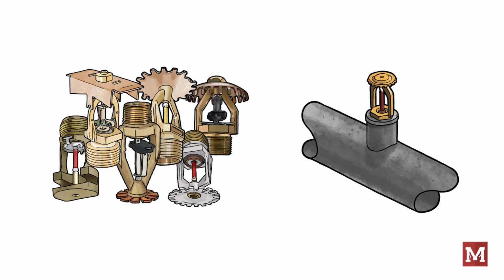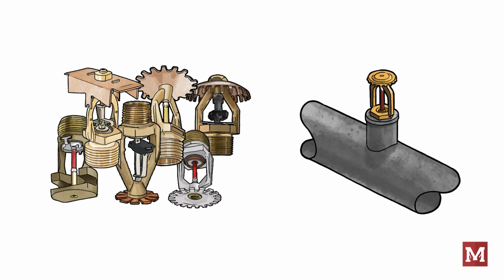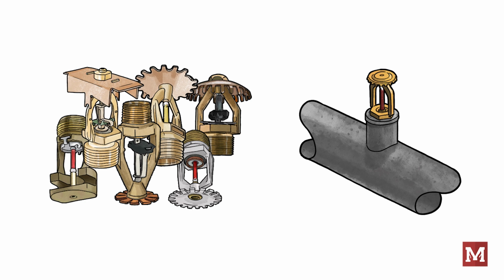Further, for non-standard spray sprinklers, extended coverage sprinklers, special application sprinklers, or sprinklers protecting high-piled storage in an ESFR system or control mode special application design, we need to know the pressure that the sprinkler needs to operate at. This can seem like a pretty insignificant data point, but it can really make a huge difference.